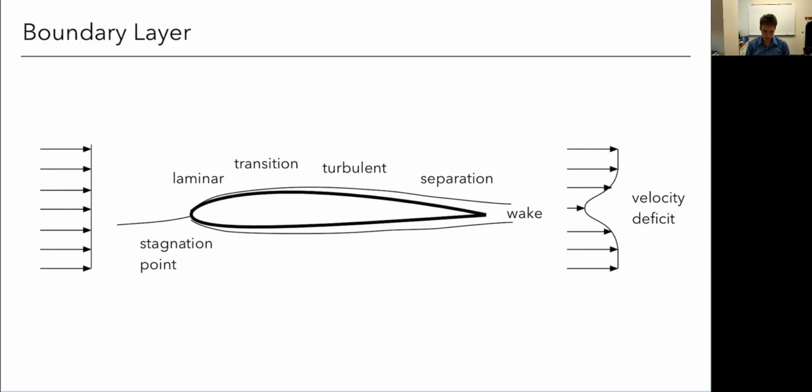The other component here is the skin friction drag. So the fluid rubbing over this surface here creates drag, which we call skin friction. Of course, drag is drag, it's a force. These are just convenient ways we compartmentalize them because of the primary drivers in them, right? So the skin friction drag is primarily driven by the surface roughness, my wetted area, the area that the fluid passes over, and so on. Whereas this profile drag, as the name suggests, is primarily driven by the shape, right? A streamlined shape will have a smaller wake, smaller profile drag.